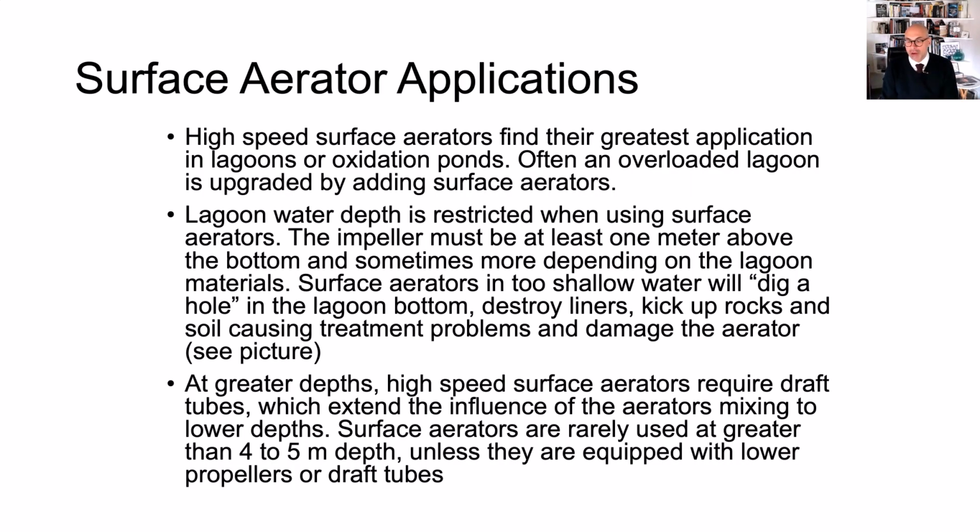Also, if you place it in a lagoon, on a float or on a dock, and the lagoon is too shallow, it ends up scouring the floor of the lagoon. That's not good, and so that's an issue. If you have little pebbles inside the lagoon for any reason, those will become like bullets once they are propelled by this propeller. So that's another issue.